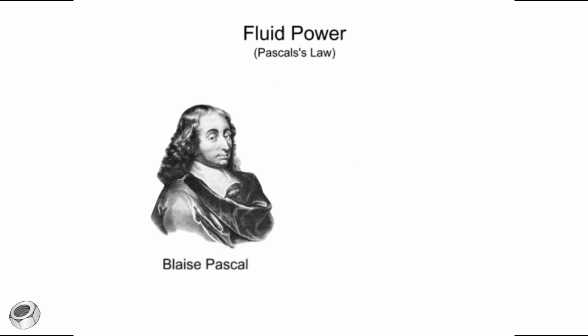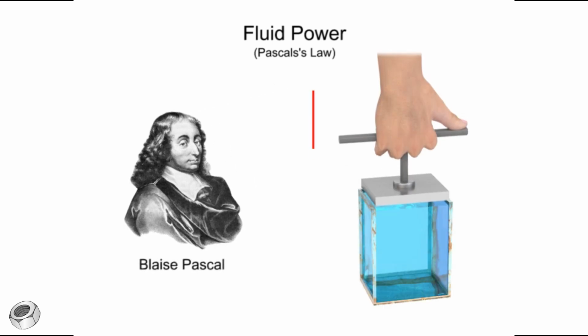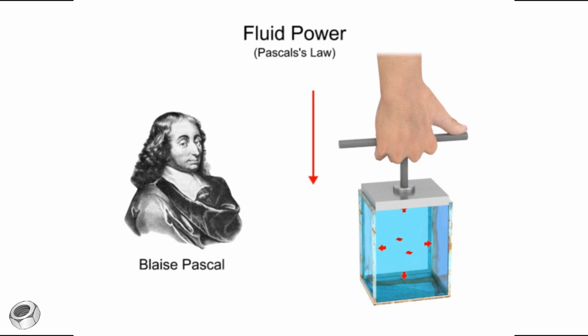Pascal determined that a contained pressurized fluid will exert pressure equally in all directions. Pascal's law states that pressure set up in a confined body of fluid acts equally in all directions and always at right angles to the containing surfaces.